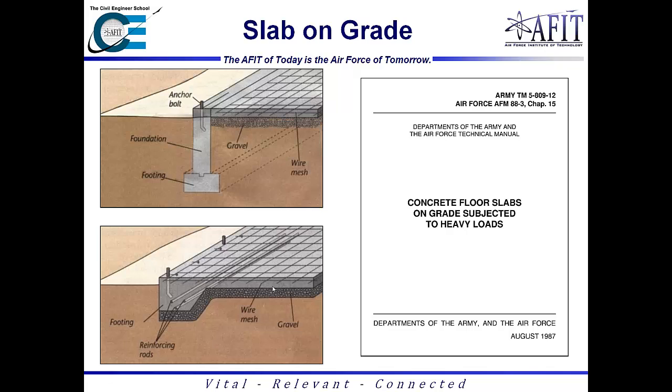Typically with slabs on grade, they're also bedded, and that can be either on a gravel layer down here or basically something that allows water to flow through. Another question you may see is when are vapor barriers needed below slabs on grade. Basically if it's in a basement or somewhere where people can easily see it, you would use it. If it's out someplace where no one's going to notice it, then you may not need it. So those are probably the key takeaways I would go with.